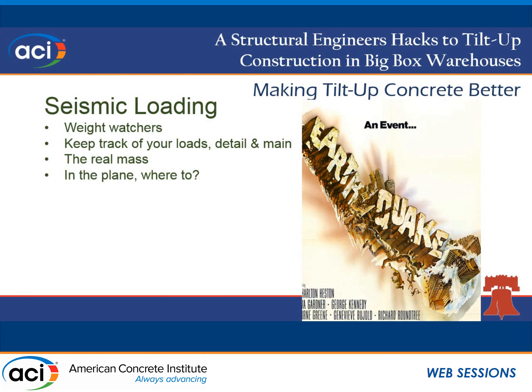So when looking at what the stiffness of my building is, I try to look at what the actual displacement of my diaphragm is and not just take a look at, if you were, say, doing a 3-story building, you might look at the drift of my brace to get an initial seismic drift. Looking at a big box, you want to look at what my maximum displacement is going to be at my roof, because that's what's your real period.